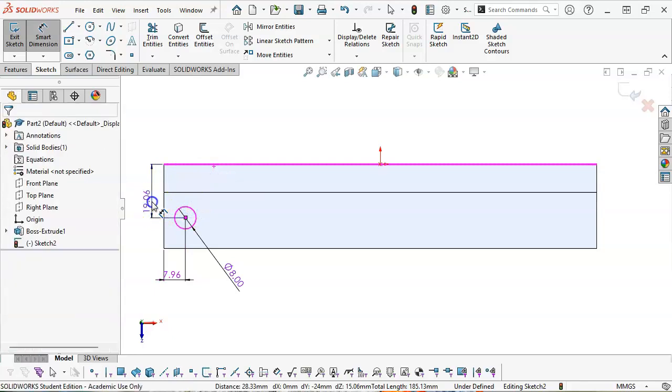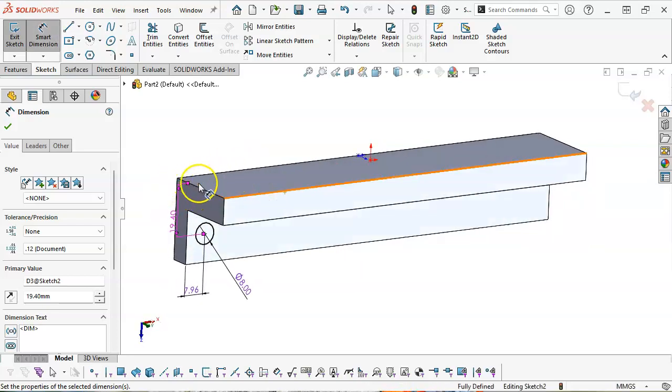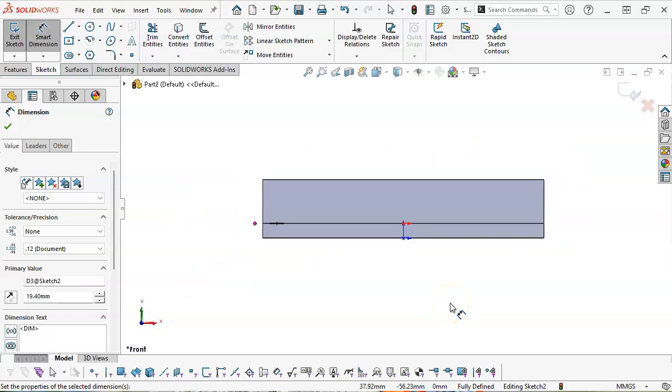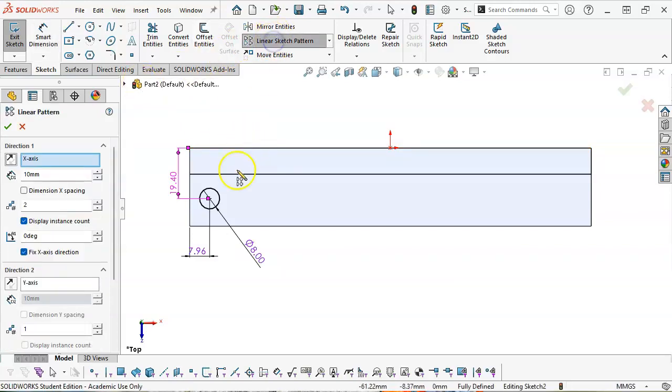So even though I'm technically picking the back top edge, because it's a projection, it will figure out where it intersects across that line, kind of in a sense like the Pierce does. It says it knows that there's a solution. We're parallel to this edge or the bottom edge, so it will go ahead and calculate it. All right, my linear sketch pattern then is 7 by 20, and that means that we have 1, 2, 3, 4, 5, 6, 7, 8 holes.